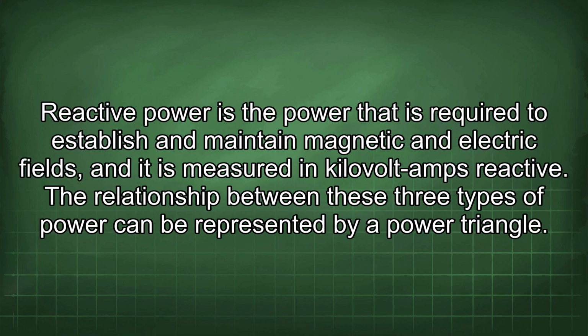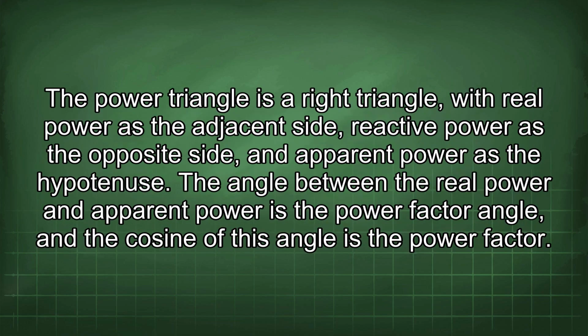Reactive power is the power that is required to establish and maintain magnetic and electric fields, and it is measured in kilovolt amps reactive. The relationship between these three types of power can be represented by a power triangle. The power triangle is a right triangle, with real power as the adjacent side, reactive power as the opposite side, and apparent power as the hypotenuse.